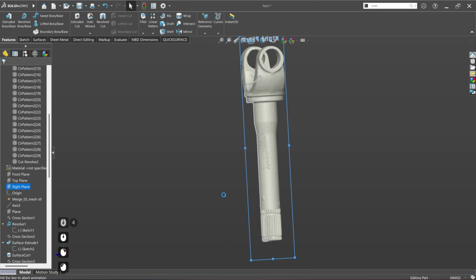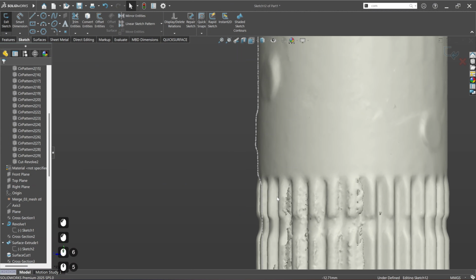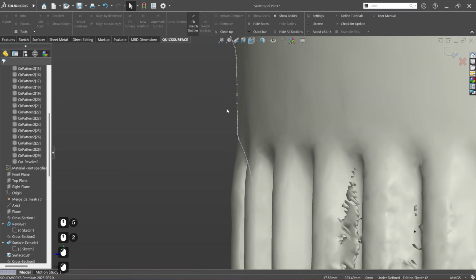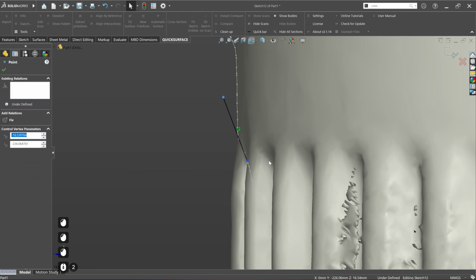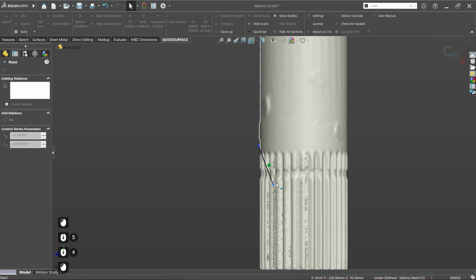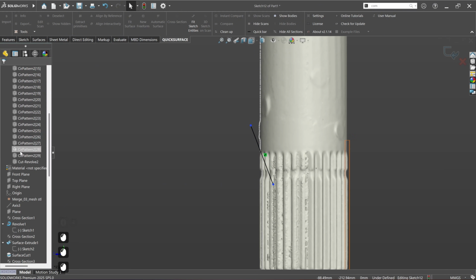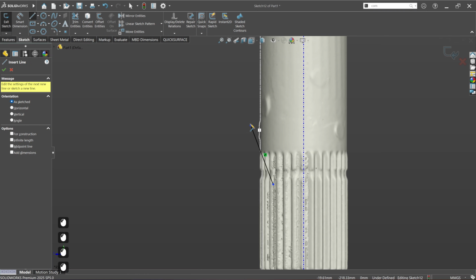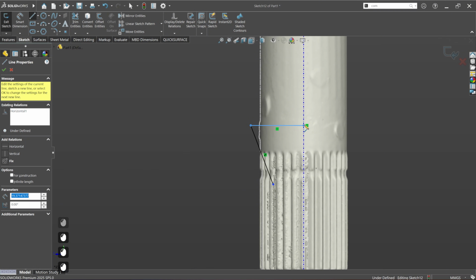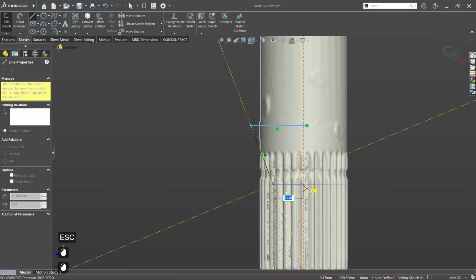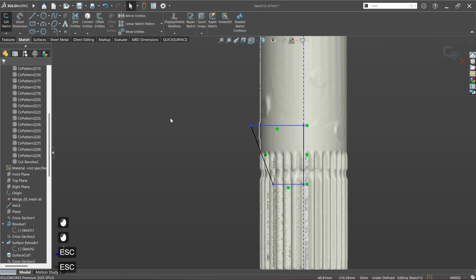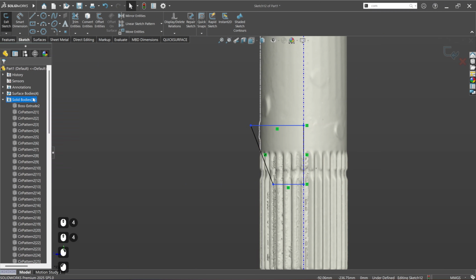Okay, so I'm creating new sketch on my right plane, coming here, fitting straight line. Okay. Let's extend this. Oh, actually, I'm going to unhide my axis and I'm going to create a revolved cut here. This will be able to save you some time.